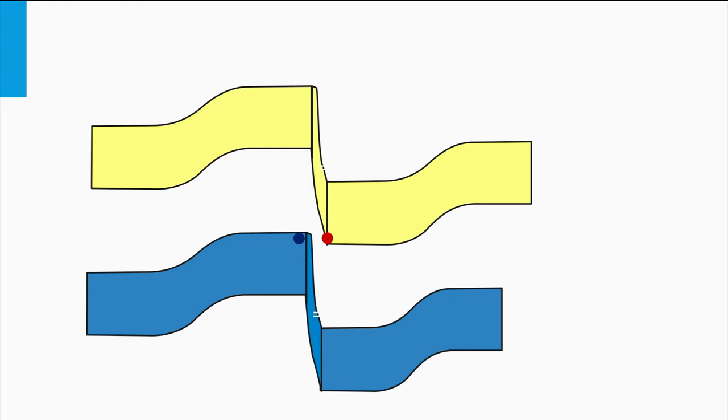The creation of such a reverse junction can be prevented by the inclusion of a so-called tunnel junction. It provides a low electrical resistance and has a high bandgap to prevent any parasitic absorption losses. The high bandgap tunnel junction is relatively thin. It means that the valence band at one side is lined up with the conduction band at the other side of the tunnel junction. The depletion zone of such a junction is extremely narrow. As a result, the slope of the valence band and conduction band are so steep that the electrons from the N layer tunnel through the small barrier to the P layer, where they recombine with the holes.